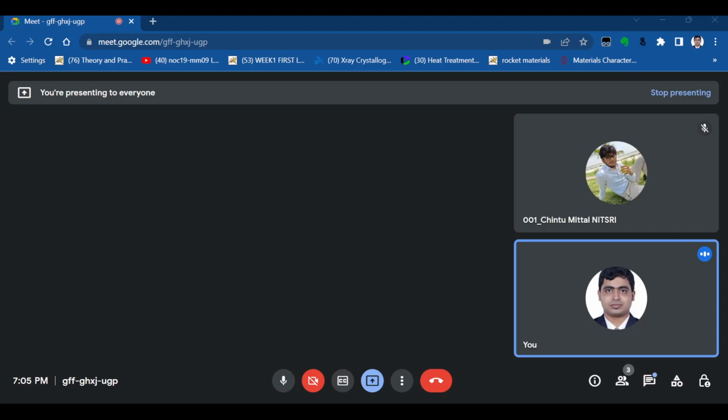Then what will happen to tau max? We know (sigma max minus sigma min) by 2. Okay, so what is your sigma max? That is sigma 1, and sigma minimum is sigma 3, which is equal to minus sigma 1, by 2.